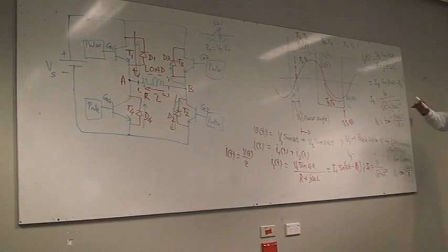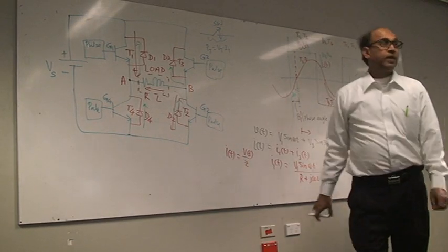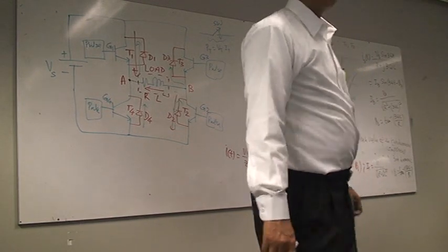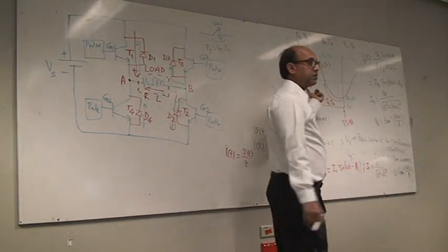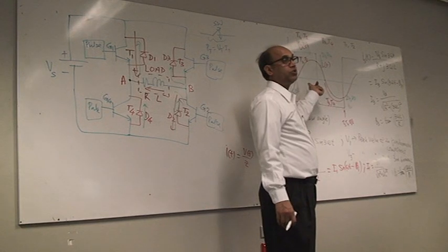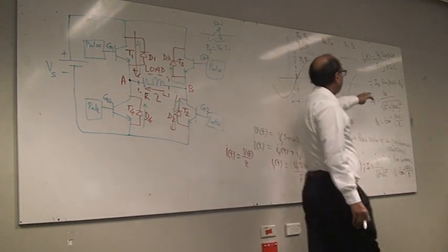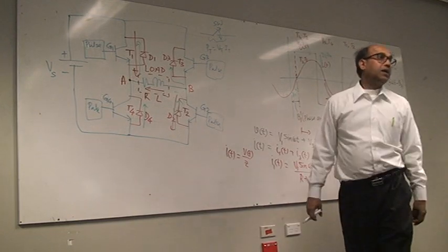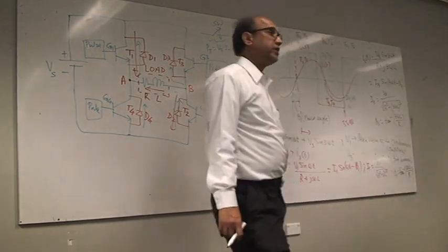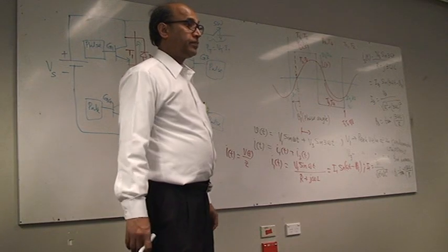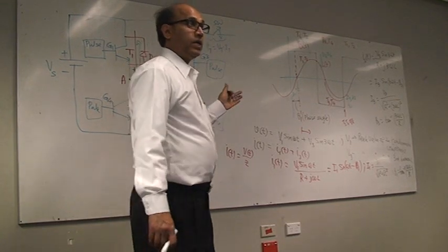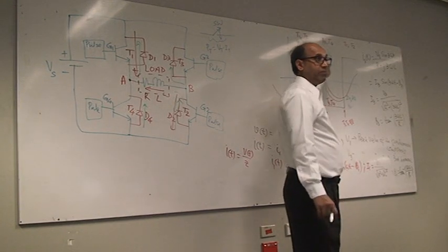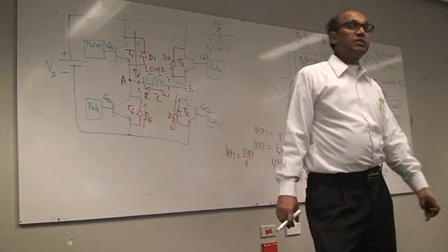Even though your voltage waveform is very crude in terms of alternating current, your current will be much closer to sinusoidal, because the impedance will not allow current for higher harmonics to flow. Do you get me? But this is of course not the voltage waveform you will see. You will see a much better voltage waveform.